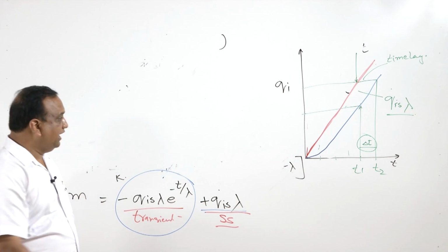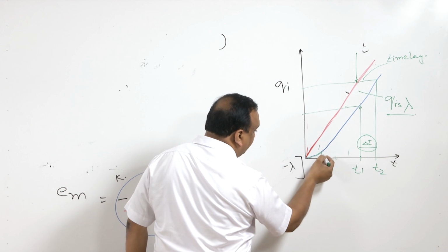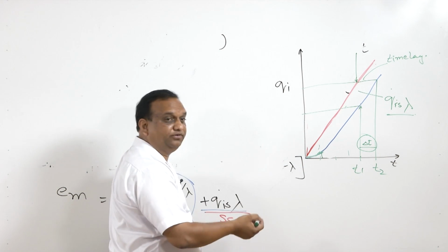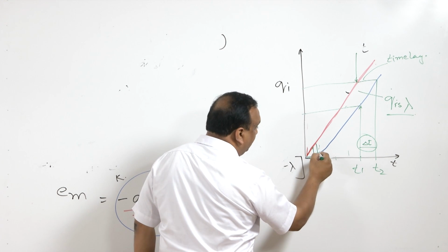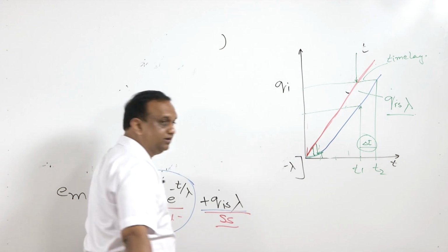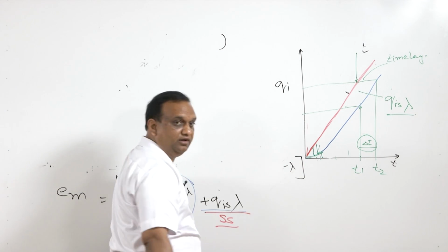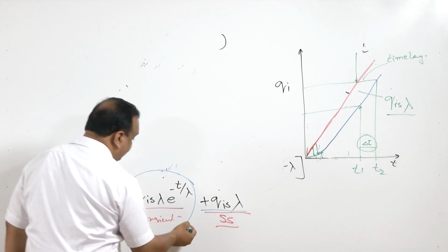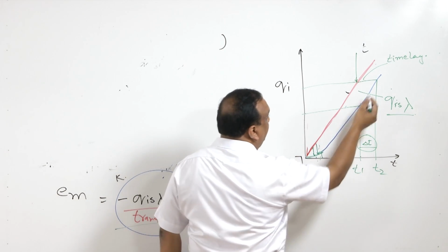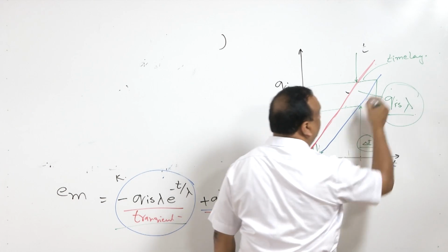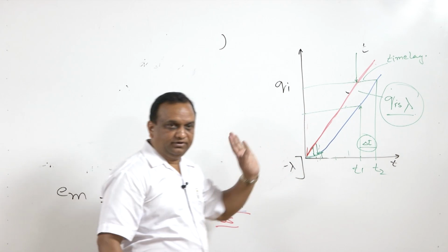There are two things, and the measurement during this time interval has to be avoided, because the variation is not linear. So what time we are making the measurement is important here. But once this transient part has diminished, anytime we can take the measurement, and we are going to have a constant error, that is Q dot, the rate of loading, multiplied by the time constant.